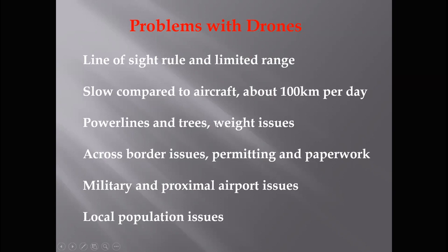Power lines and trees are a problem. We have smacked trees in Angola, and we have put our drone and our bird into power lines. So one of the things you have to do before you do anything is fly a very accurate digital terrain model with LiDAR. Create your own digital terrain. In the software, tell it that it must drape this by 25 meters, which is the highest tree in the area, or you can use obstacle avoidance, which has forward-looking cameras. And when the drone sees something coming up like a tree, theoretically, it's able to go around it. But in practice, it doesn't always work.